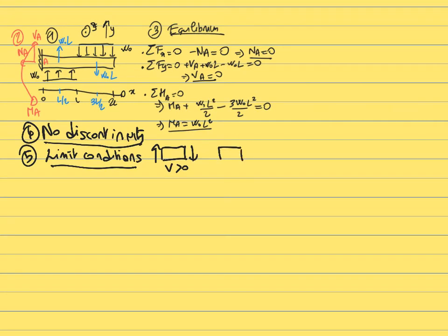For the moment we use the smiling convention: a positive moment is a moment that would make the beam have a smiley face with a convex shape. So now we can express the limit condition based on the value of the unknowns just by making sure we are using the right sign convention.